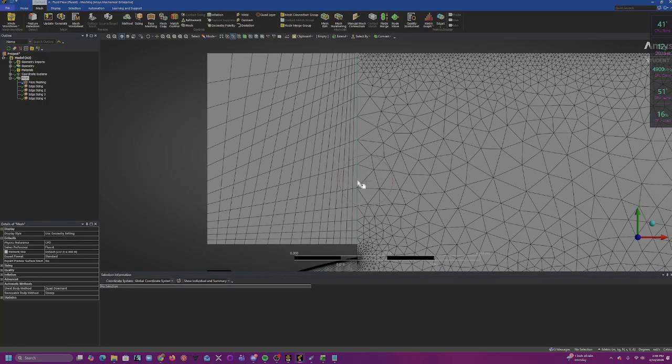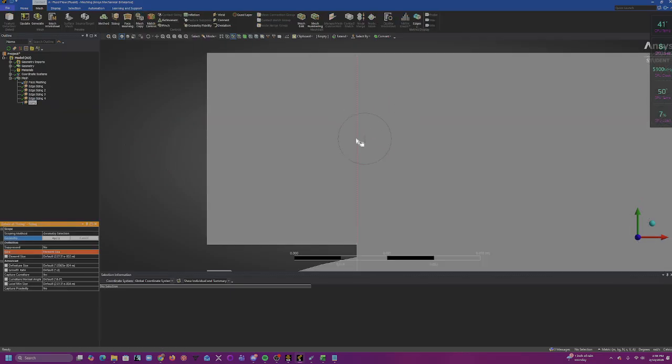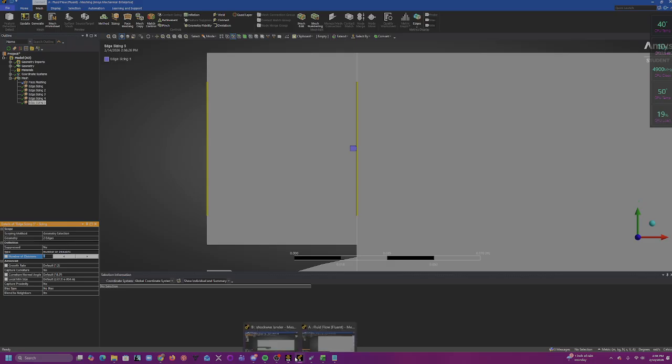So now we can move on to this section right here. So go ahead and click sizing again. We can start off with these two vertical lines. Just click and drag and make sure they are green. Then we can click apply. All right. Go ahead to element size, change that to divisions. This one, let's go back to my notes.